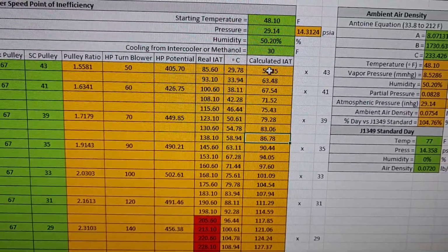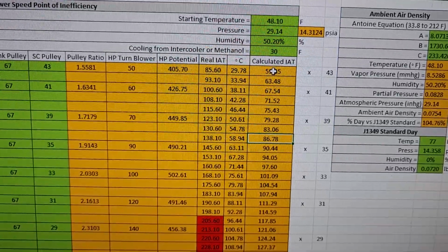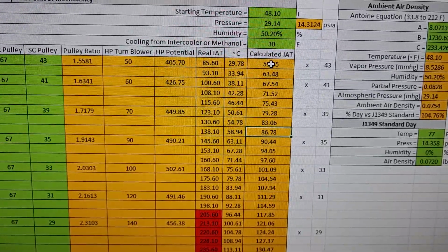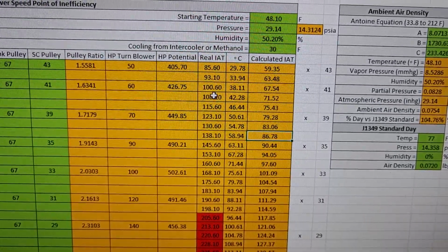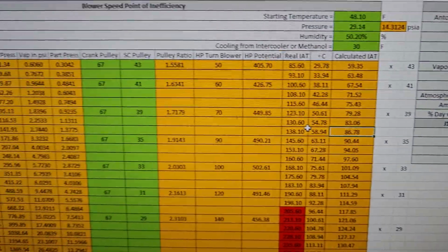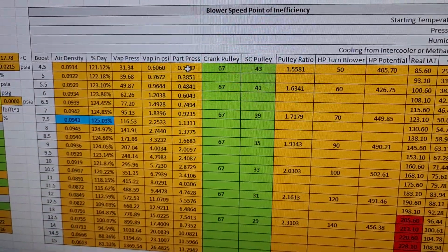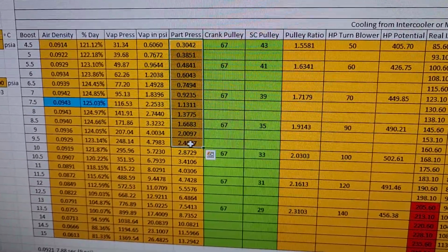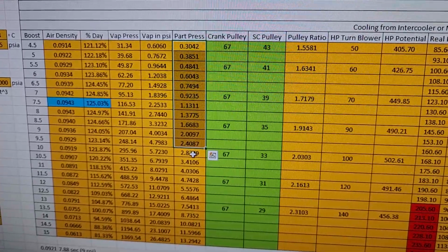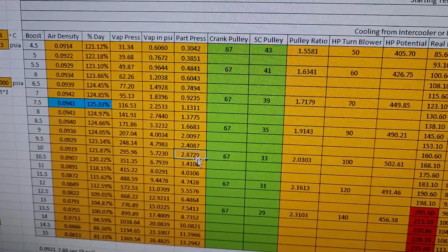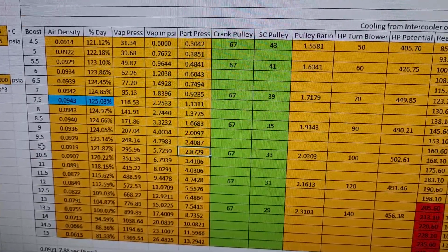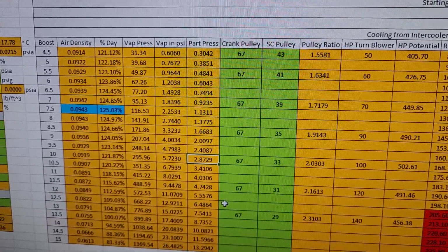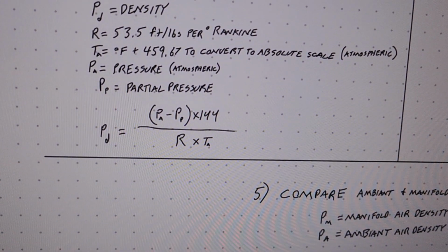But because that supercharger is in a heat-soaked environment and the rotors get hot, the casing gets hot, and everything heats up, it expands more and generates more pressure and more heat. And that's where this partial pressure comes in. So what you're looking at here is how many pounds of boost you're generating that is not being used to make horsepower. So at 10 pounds of boost, my effective boost is basically 10 minus this number. Okay, and that's really what you're getting into here.